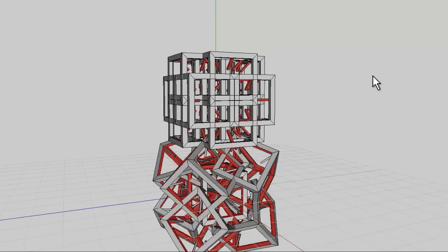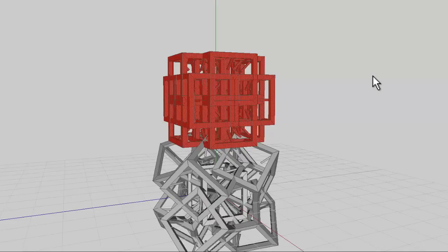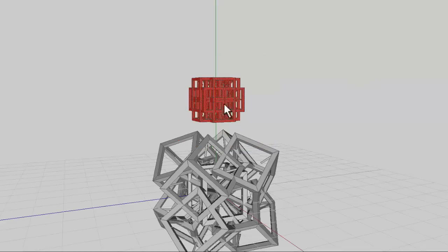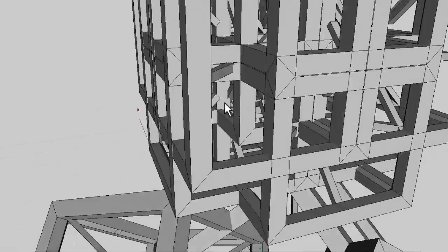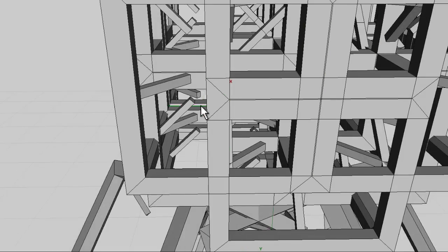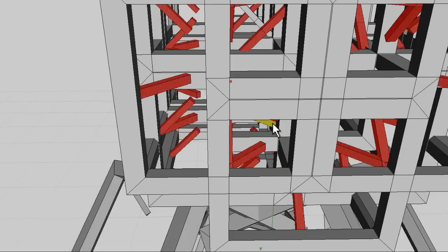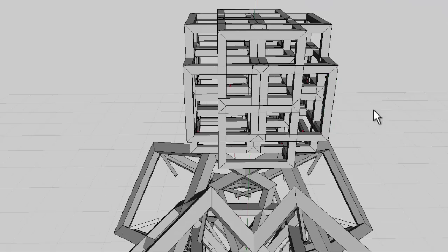So Control Z, just to show you that, if you hold Control and Alt down, you can take it further steps backwards, which is worth knowing. So Control, Alt and Z will take me back to the unscaled position. I can get rid of the sticks in this scaled down version here. So select an internal face, press identical, press plus, press delete. That's got rid of those.